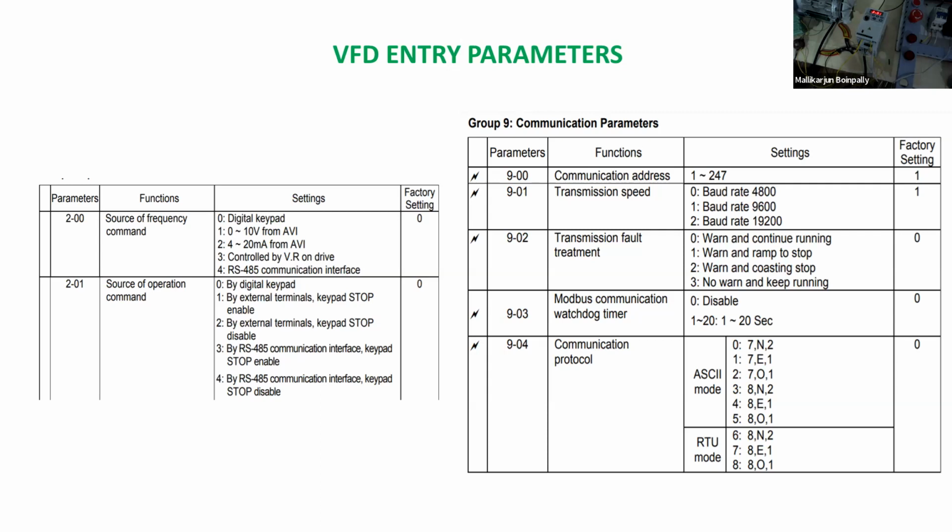Okay. Now it is going to vary based on this speed itself, right? When I vary the speed with the potentiometer itself, it is going to vary. I'm going to vary this one now. Okay. Even if I vary this, speed increasing. This is speed decreasing. Okay. Like that, we can increase and decrease the speed of the motors. Okay. Hope you understood, right?